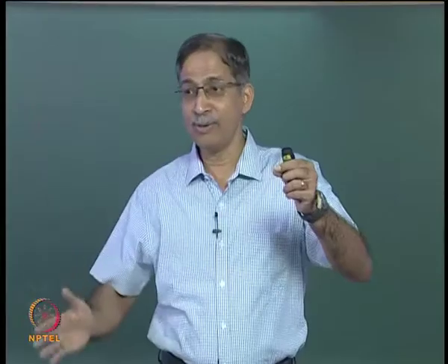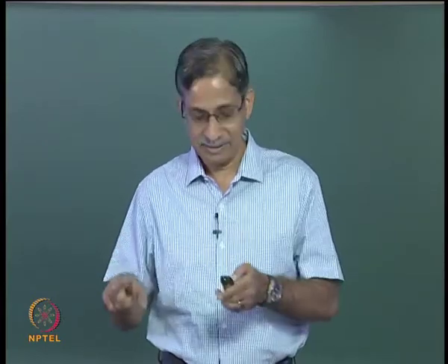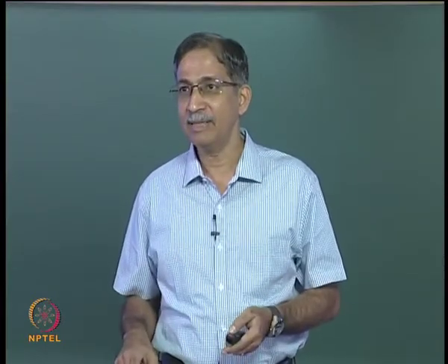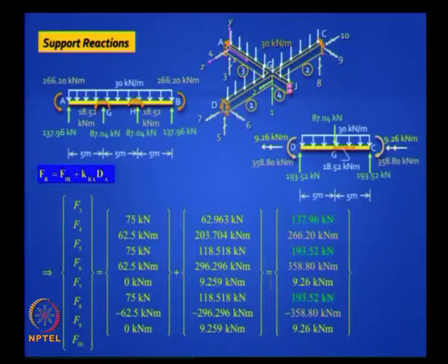at the guided roller support, we are finding the deflection at the guided roller support, not at D1. Please note, we are finding the deflection at J. So at J you get something more than what you get at G. What's the additional thing you get? It's the slope into span by 2, you can prove for a cantilever. So you have to do it very carefully and work out the deflections.